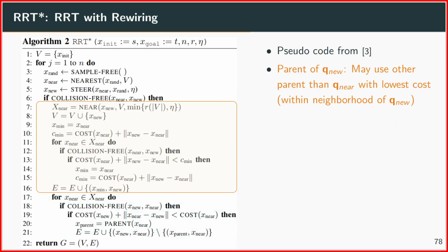So what you can still see here up here, the pseudocode looks exactly like the pseudocode which we saw in the first slide on RRT. What we do here is that we sample a configuration in your configuration space, we find the nearest in your tree, we steer the tree towards this new configuration, and we have this parameter mu here, which tells us how far we should actually steer our tree. And so nothing new here.